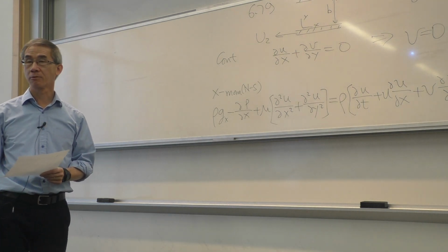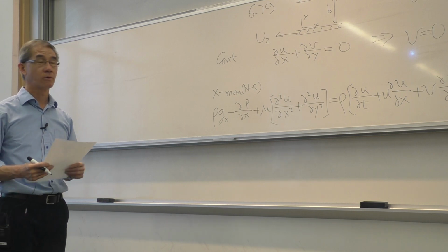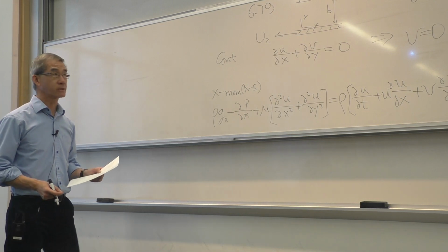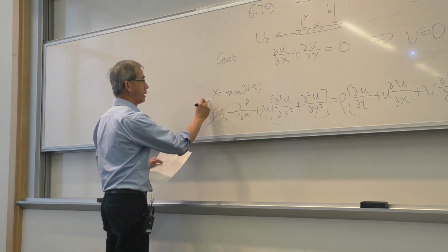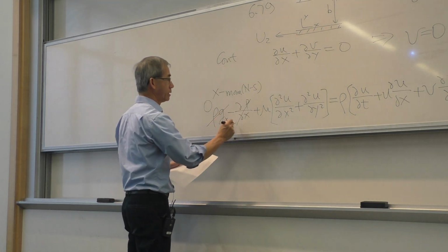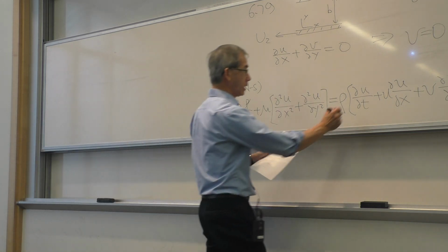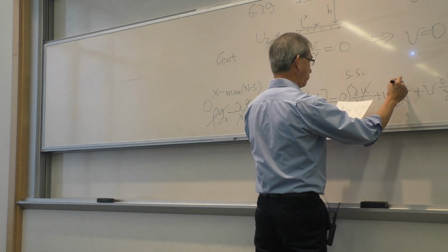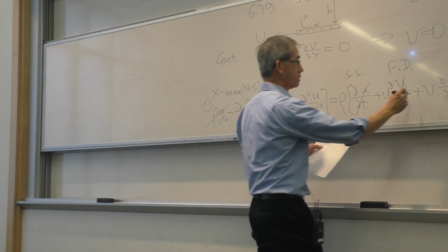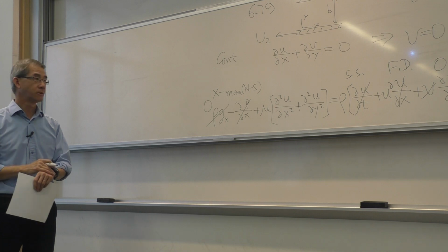Anyone who has not been able to come to this conclusion, you need that to finish the second part, for which you will have to simplify the Navier-Stokes momentum equation in the x direction. There's gravity, but there's nothing in the x direction, so that's zero. You are told there's no pressure gradient in this problem. That's also zero. On the right-hand side: steady, fully developed, FD, and the velocity V is zero. So the right-hand side is practically all zero.